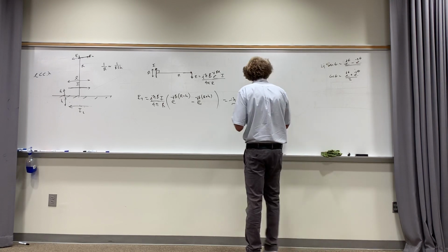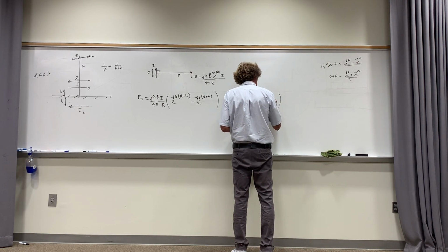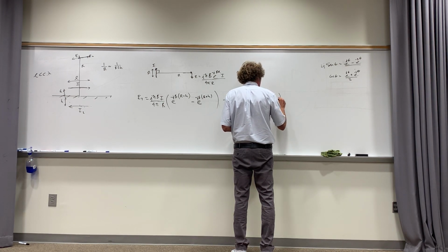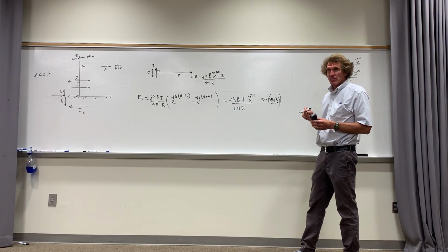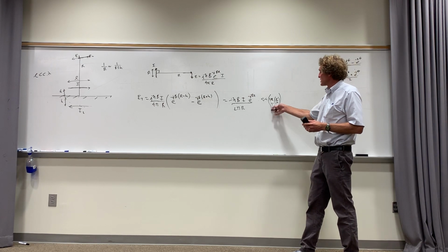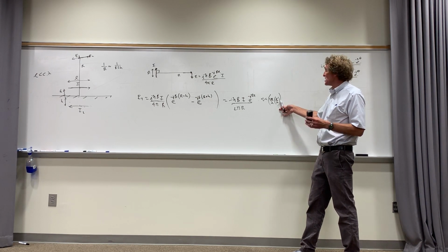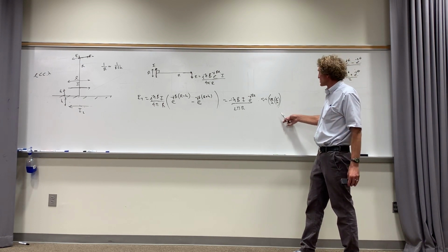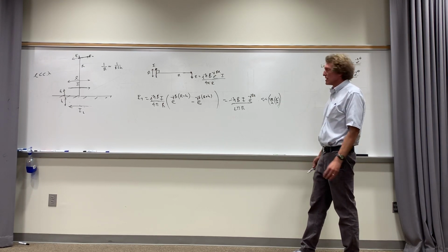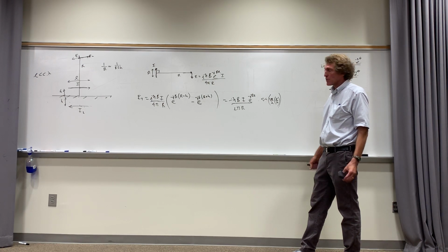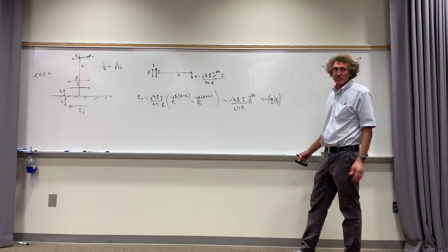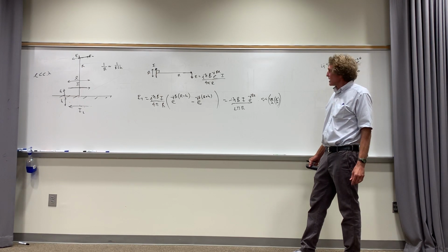But if you put beta as simply 2 pi over lambda, and then you put the length of the antenna in terms of L over lambda, now you can do something with that. And furthermore, you can make the argument that if this is small in terms of radians, then the sine of x is about x. So you can simply put down 2 pi over lambda times the length of the line in lambda. Follow me? Or you could just put beta times L. Either one. Agreed, class? Just remember that.